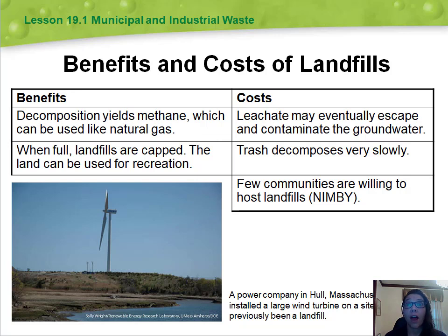It also has a gravel layer above that hydraulic barrier that drains water. It lessens the pressure on the hydraulic barrier. A soil barrier of at least 2 feet stores water and protects the hydraulic layer from weather extremes, and a topsoil layer of about 6 inches encourages plant growth and prevents erosion.